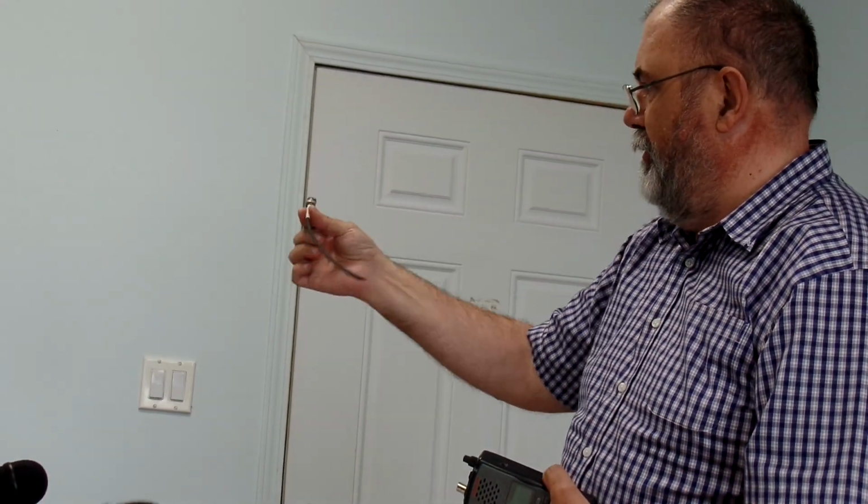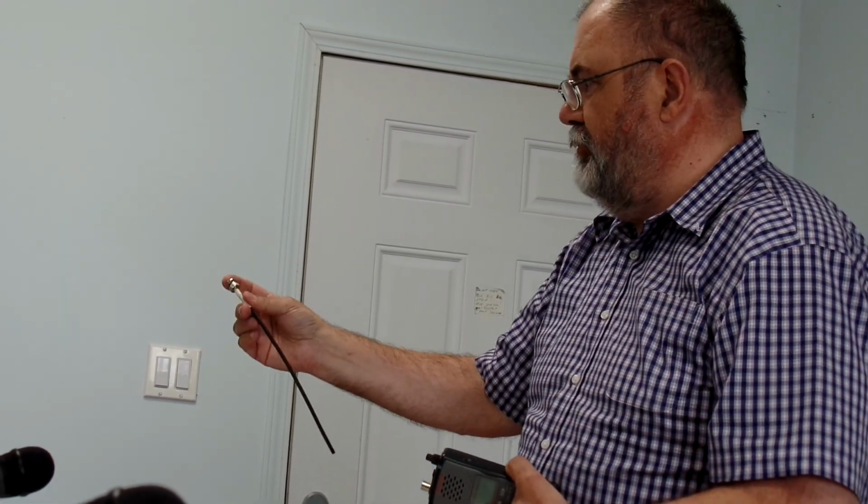So very, very handy if you're getting intermod, especially in your base station at home, and every time you hear intermod, you hear the Weather Channel. Well, you know that one of the frequencies that's giving you a problem is 162.4. So you can prepare one of these, which cost all of $2, because this is a cheap Chinese connector. No, I think the heat shrink tubing was worth more than the connector. So that's a way that we can just completely eliminate a station.